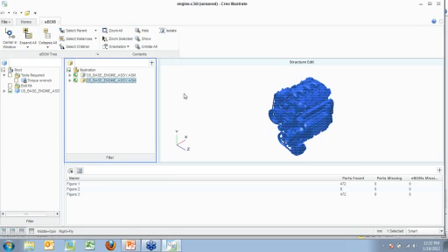But then I can actually create an assembly within CreoIllustrate. It might be more beneficial to create an assembly outside of CreoIllustrate, depending on the assembly. If it's several thousand components, I would say you might be better off doing an assembly outside and then importing that assembly in. But if it's a smaller assembly, let's say I want to put that suspension component in here. That suspension component was only 100 parts or so. Then I could import that in and show them both at the same time.